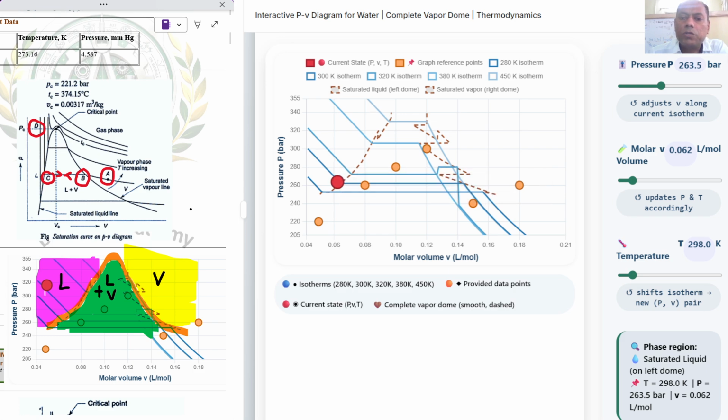Now the position of the dot is at C, which means the vapor has completely liquefied. Now again increase the pressure. What will happen now? The slope becomes almost vertical, the change in pressure happening at a very rapid rate. Why? Because compressing the liquid is very tough compared to compressing the vapor.